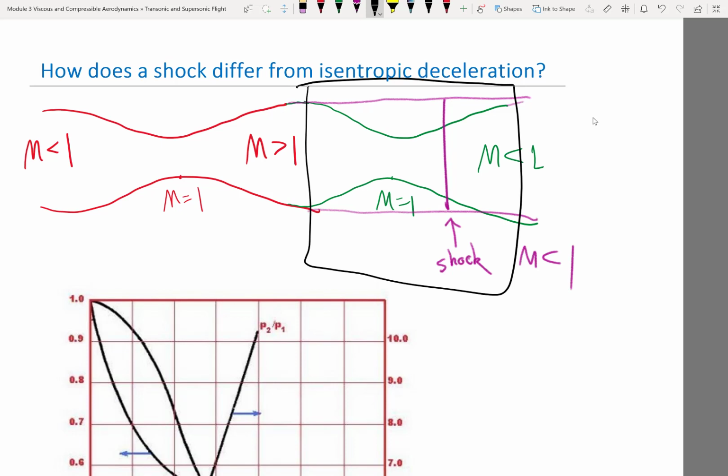Increase the thrust, right? Okay, so that means there is an external force, in which case? Green case or purple case? The green case, right? There is an axial force due to the difference in the pressure between the convergent section and divergent section. Which section has higher pressure? The subsonic section or the supersonic section? The subsonic section has higher pressure, right?